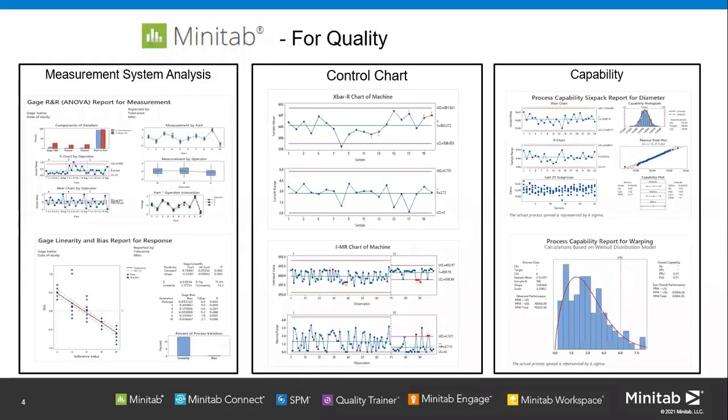So these are example tools available in Minitab Statistical Software. We have measurement system analysis: gauge study, gauge R&R, repeatability, and linearity, because in MSA we not only cover precision, we also rely on the accuracy part. We also have control charts, not only the S-bar chart but also the T chart and EWMA, advanced control charts also available in Minitab.